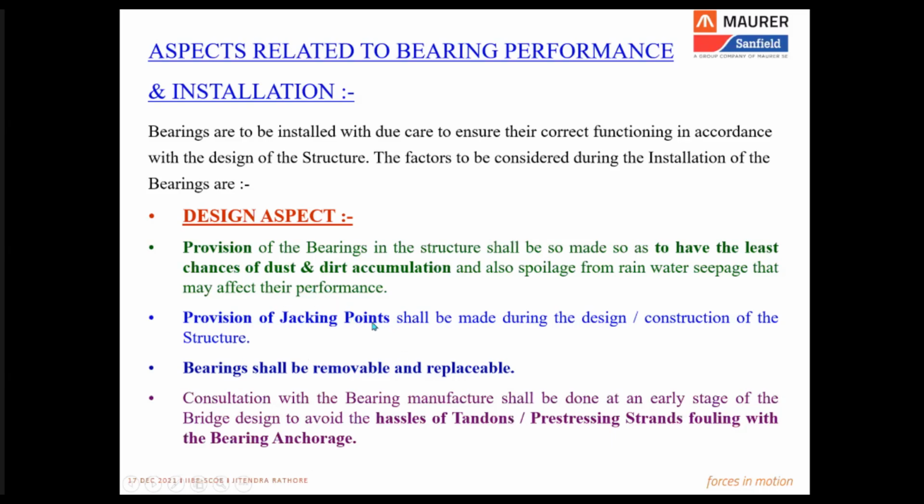There shall be adequate provision of jacking points in the structure because no matter how good you design the bearings, there are always contingencies and there may be an unforeseen situation where you need to take the bearing out for some repair work or some replacement. So the jacking provision should be there in the structure and the bearing shall be so installed that they shall be removable and completely replaceable.